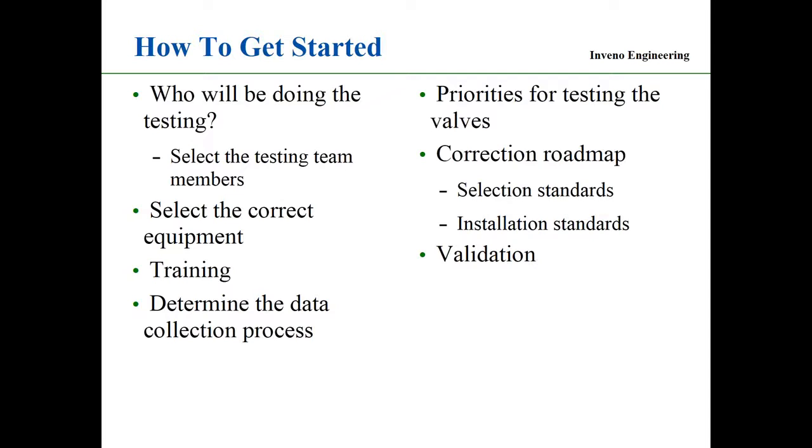Where do I collect the data? How do I collect the data? The thing is that priorities for testing the valves. If I have to go out and test 20 bypass valves, and I come back and 10 of them are leaking, what degree of leakage? So I set priorities. The ones with the highest ultrasonic level or flow are the ones I'm going to do first. The ones with very low ultrasonic levels are lower priority. So I set priorities depending on my test results.